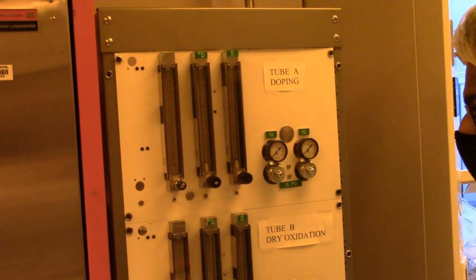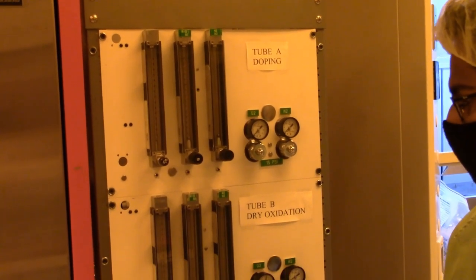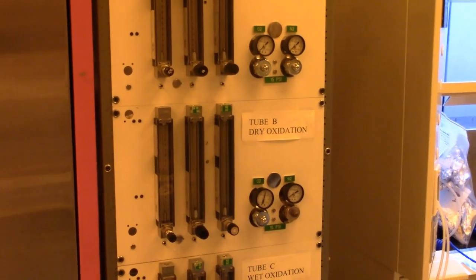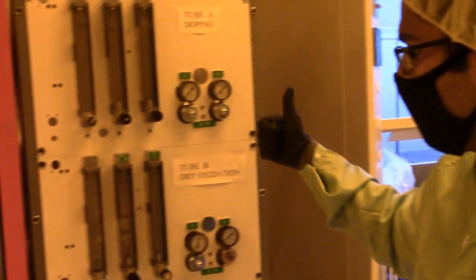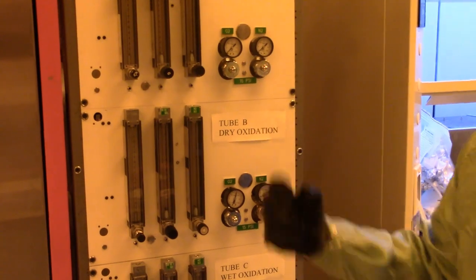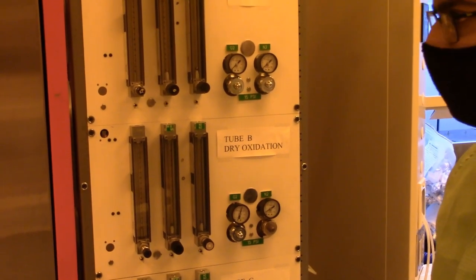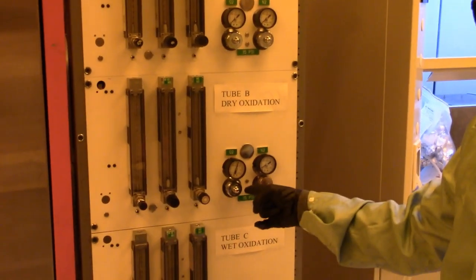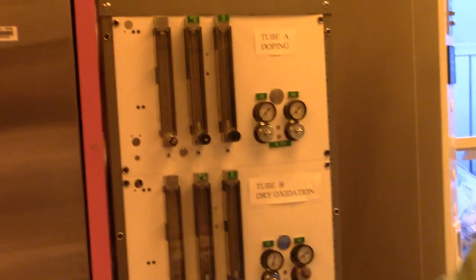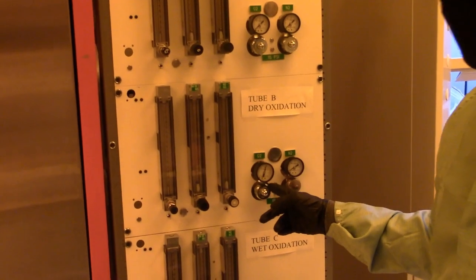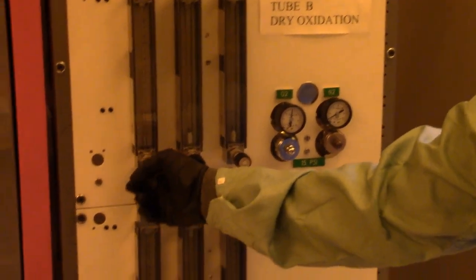The other component that you need to make sure of before you start your oxidation step is oxygen flow. The oxygen comes in from a cylinder that's in the service bay. There are two metrics you need to keep in mind while flowing oxygen. One is the inlet pressure at which it goes into the furnace, and the other is the flow rate.